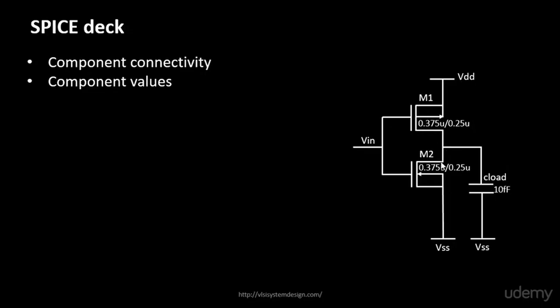Ideally, your PMOS should be twice or thrice bigger than your NMOS, by that I mean 0.375 multiplied by 2, in that range. But there are reasons and applications for both of them. You need this kind of inverter, as well as an inverter which has a PMOS bigger in size. You need both kinds of inverters for your application. We'll get into those in a bit. For now, we'll just look into the PMOS and the NMOS of the same size and see what happens to the characteristics.